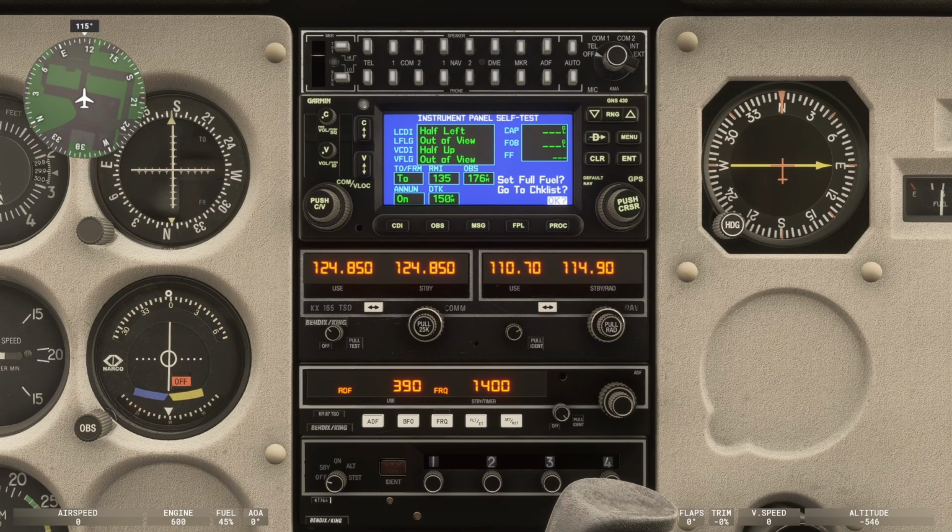And that also means in this case that the vertical navigation signal, for example, the glide slope or the GPS vertical guidance, is valid and functioning properly, right? So VFLG stands for vertical flag, and it indicates the status of the vertical navigation system. So L from lateral, V from vertical.